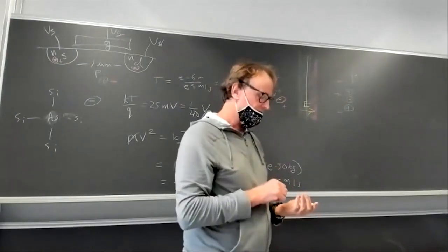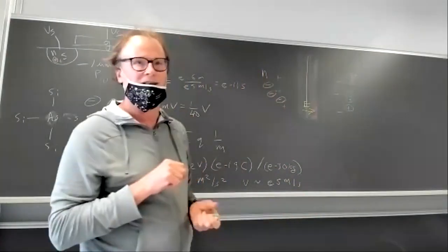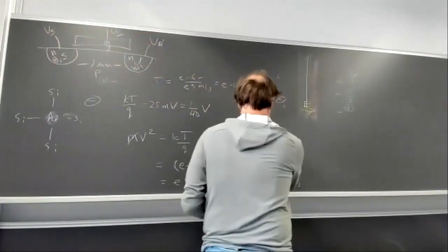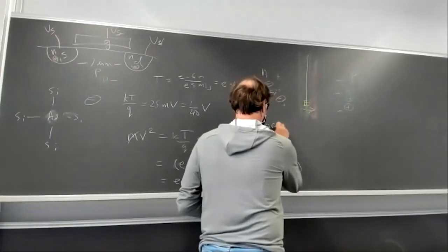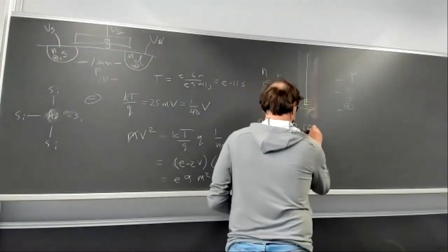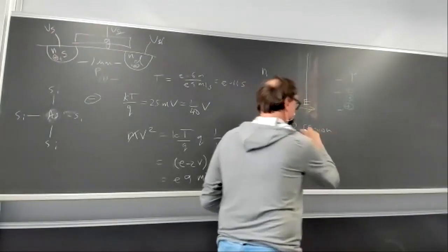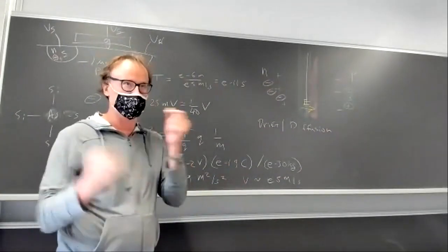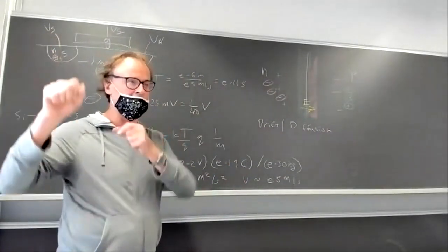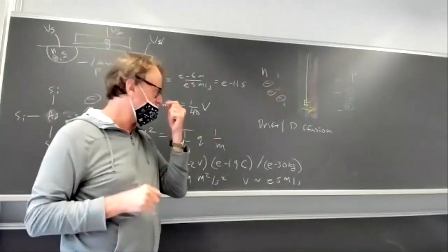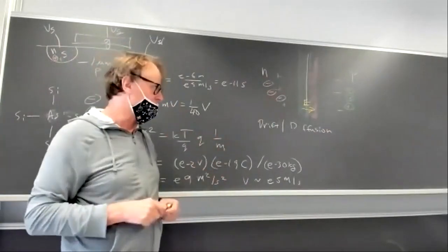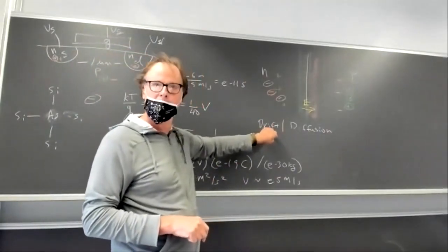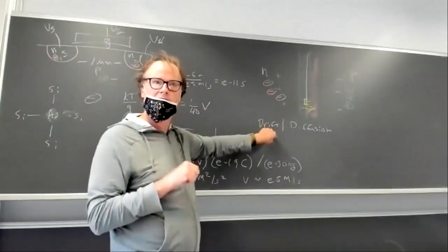And so I forgot to tell you one important thing. How can charge move around in the semiconductor? There are two mechanisms: drift and diffusion. I just told you about the diffusion mechanism. If there's a concentration gradient, that causes a net flow of the carriers, just because they're whizzing around at high speed. If there's lots somewhere, they'll whiz to where there's less, just to equalize it. The other way the charge can move, because it's charged, is because an electric field acts on it. That's drift current. Is it clear what the difference is?